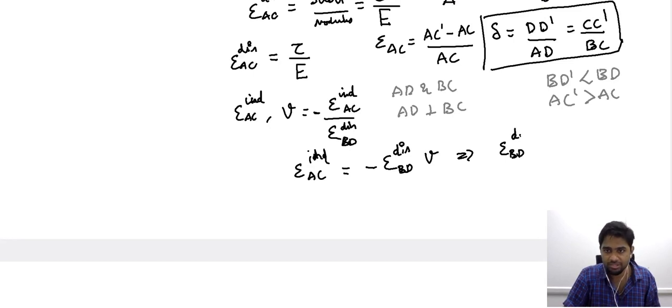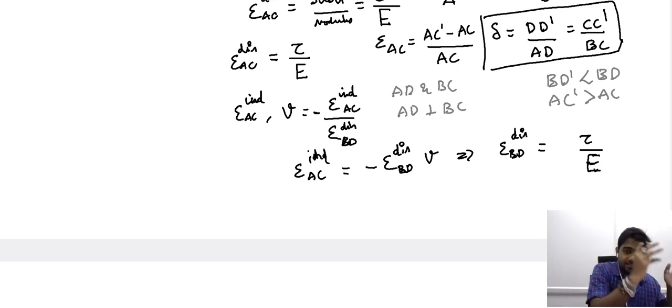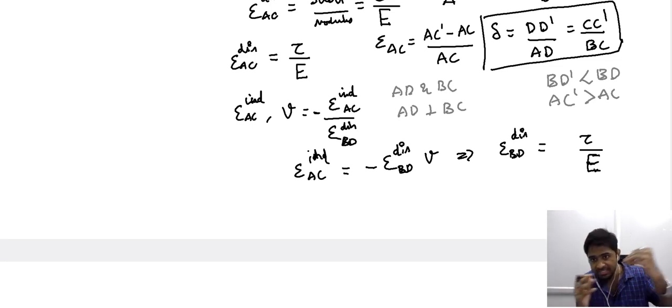So we are considering the direct strain here. It is the ratio of the stress the particular sample experiences with respect to the corresponding moduli, and here again we are considering a compressive sort of a deformation, so the modulus remains the same, and the only stress that we are considering is the shear stress. The only stress that has been imposed is the shear stress. The reason why we have compressive action because of the shear stress is because this shear stress translates itself to the compressive load along this particular element.